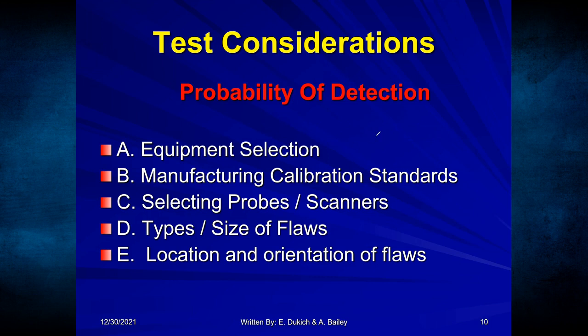And am I going to use radiography, ultrasonics, or another technique that's more sensitive, because they're coming out with other things that are better, like shearography testing or thermography. And maybe I'll show you guys something like that next year if I'm invited to present. So for the equipment that I've selected, I need a calibration standard. The calibration standard tells me, do I have enough sensitivity using this test to find the flaw of interest?